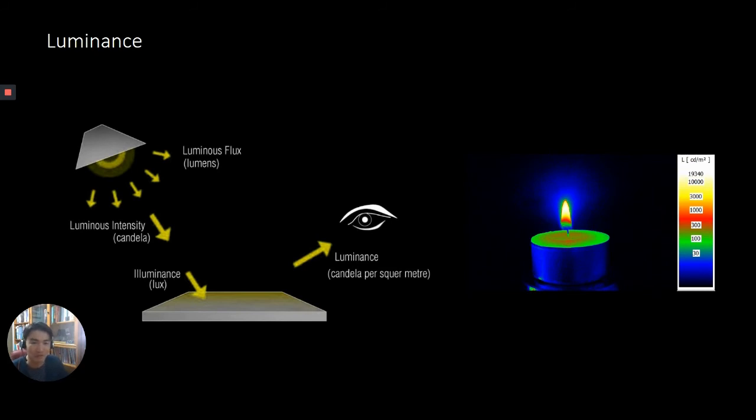The brightness of an object refers to the perception of a human observer, while the object's luminance refers to the objective measurement of a light meter. The perception of brightness is a function of the object's actual luminance, the adaptation of our eyes, and the brightness of adjacent objects. Although the words are interchangeable much of the time, under certain conditions a significant discrepancy exists between what we see, which is brightness, and what a light meter reads, which is luminance.